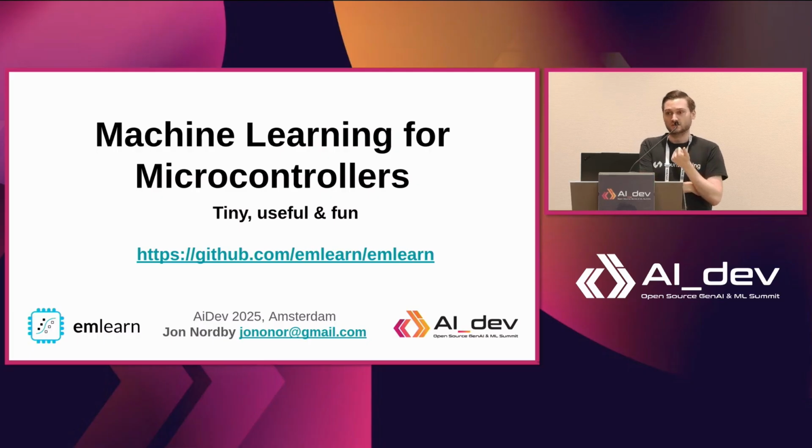Yes, it is quite relevant. ARM Cortex M4 is quite established, almost a 10-year-old microcontroller now, very typical to use. That has an okay instruction set for SIMD, so usually you can do 8-bit, 4 at a time, and that's quite useful.